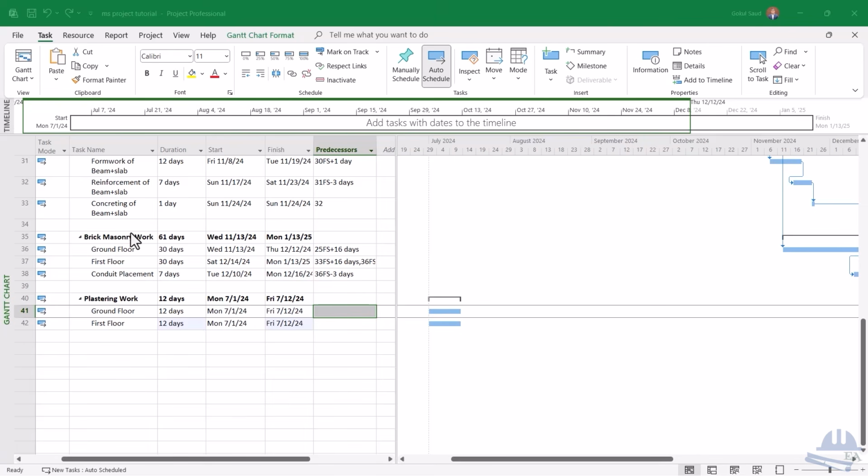If you do not cure the brick wall, the brick will absorb the moisture from the plaster, and the plaster will not be strong enough, because the moisture required for the hydration of the cement is all taken by the bricks.